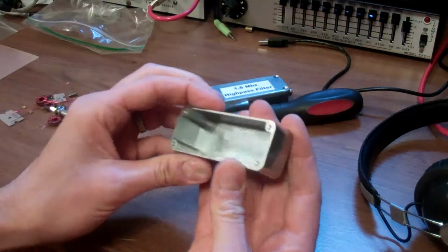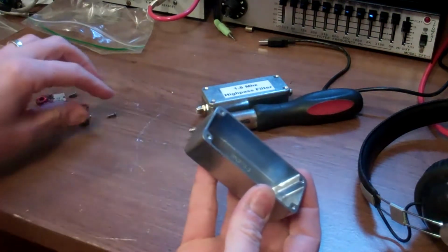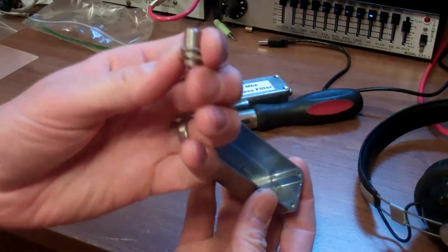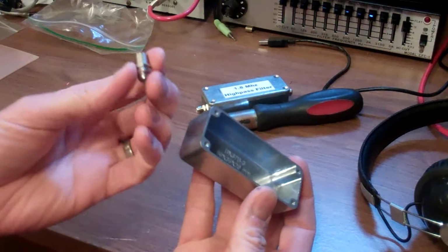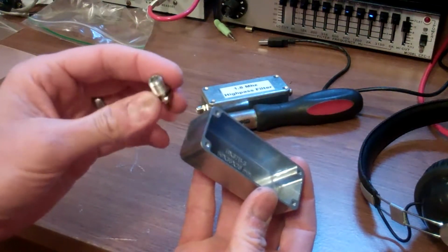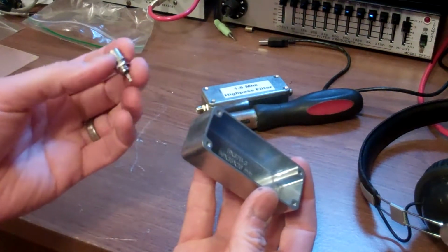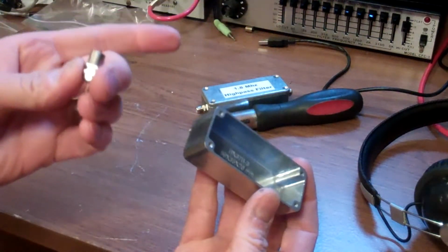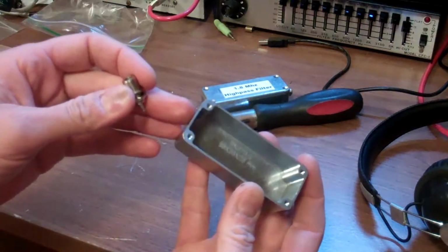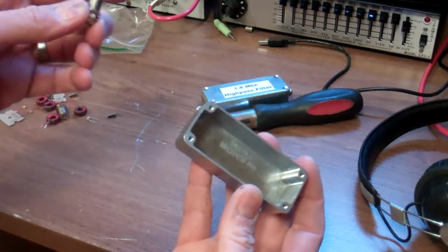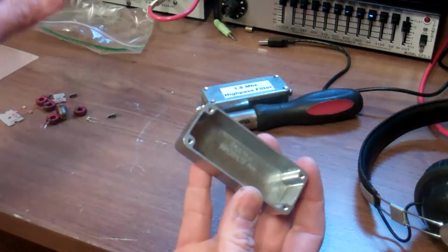Before I start the actual construction, I'll drill the holes in the ends to put in my connectors. I like using these F-type connectors because I use 75 ohm coax for all my connections on my radios. My Hammerlund SB600 has a 90 ohm impedance, and most of my other ones I either have step up or step down transformers depending on how I'm using it.